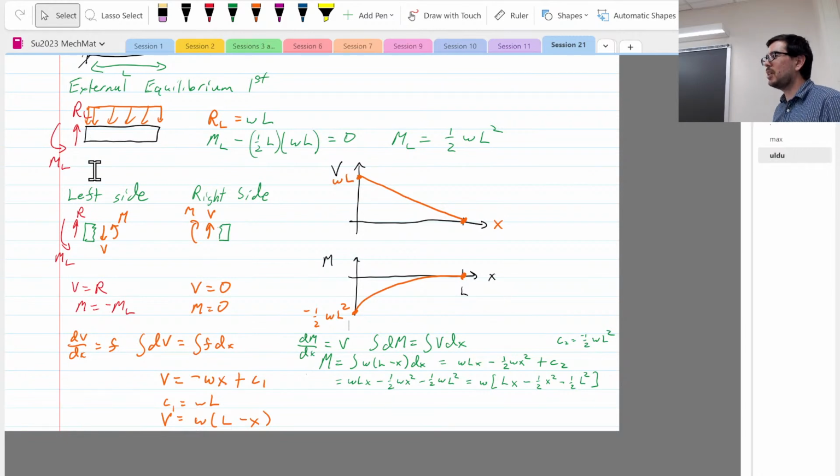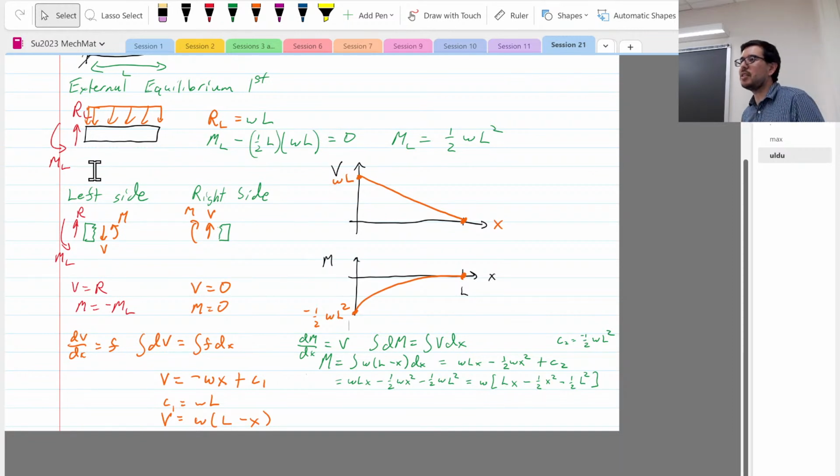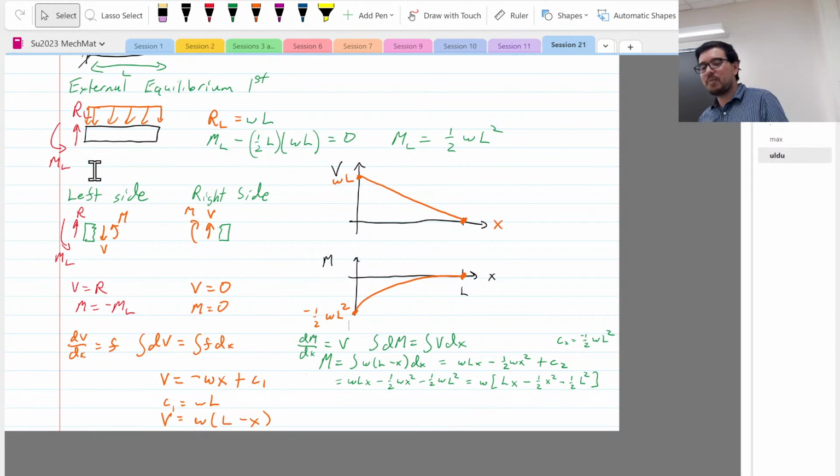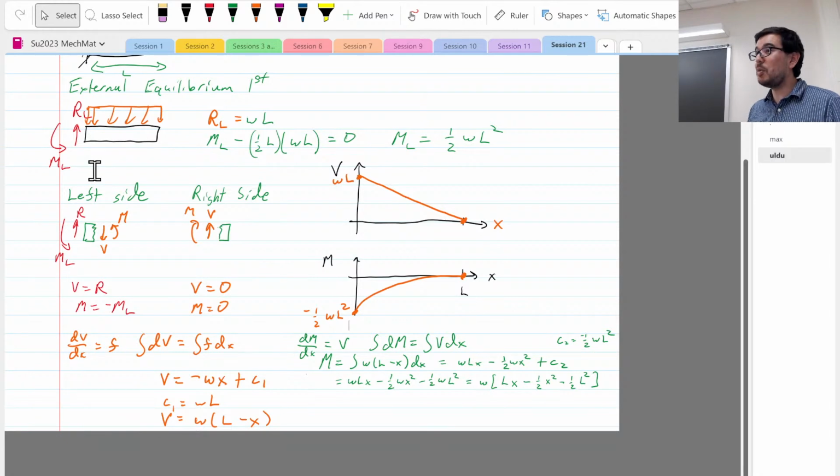We're focusing mostly, I mean, it's possible, but we're focusing more on the stresses in this part of the class. Now, do you need to know how to use compatibility to figure out stresses sometimes? Absolutely, because you can't figure out what the internal moments or the forces might be if you have an overconstrained problem.